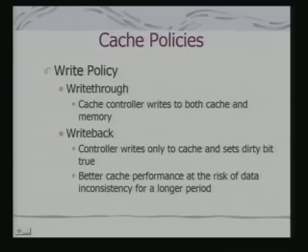In a write through policy, the cache controller writes to both cache and memory at the same time. A variant of this policy would be writing to cache as well as to the write buffer, so that it can be emptied later on, but it will not wait. That means the cache controller is not waiting for the write process to be initiated till a block eviction takes place.